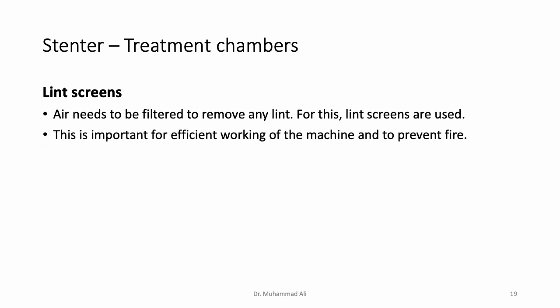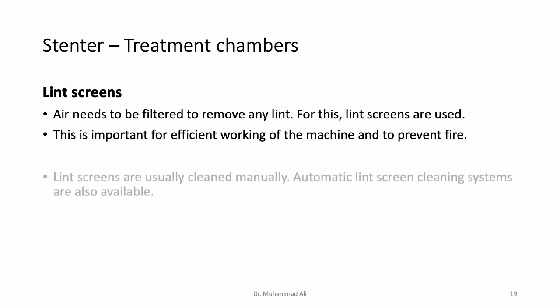Although it's a simple filter, it's very important for the efficient working of the machine, and to prevent any fire. If the lint screens are choked up with fluff, then the airflow through the lint screen will not be proper, and therefore the efficiency of the machine will decrease. Similarly, if the lint screens are not properly removing the lint, then there is a chance that if it builds up in the air, it can catch fire, of course.